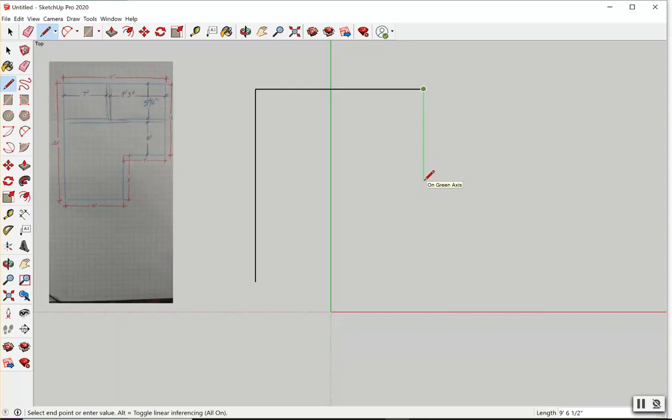So moving down to the next, I'm going to type in 12 feet. And I'm just simply typing it in once I'm moving the direction that I will need to. As you can see, your length is populating over here in your right hand measurement box at the bottom of your screen. That next distance, as seen here, is 7 feet. And I'm doing all of our measurements that are in red. 8 feet. And I'm simply pressing enter. And I can either pop right to my endpoint or I can type in that measurement, which is 10 feet.